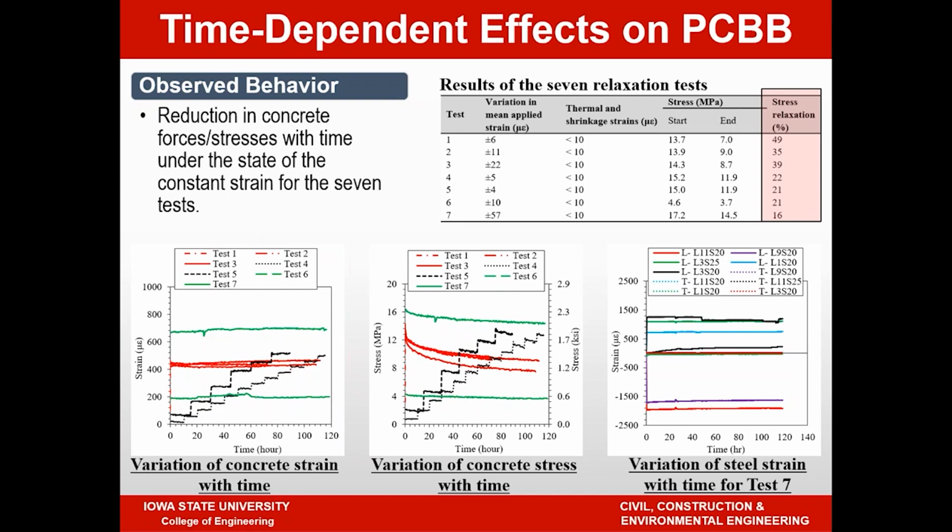The black line shows a step function. Purposely, in these 2 cases, we applied the initial stress in steps because this is what a typical column would experience. In a gradual fashion, the strain buildup will take place, but yet one would expect some losses in the stresses because the relaxation takes place. So the left-hand side shows that we managed to maintain the strains as constant as possible.